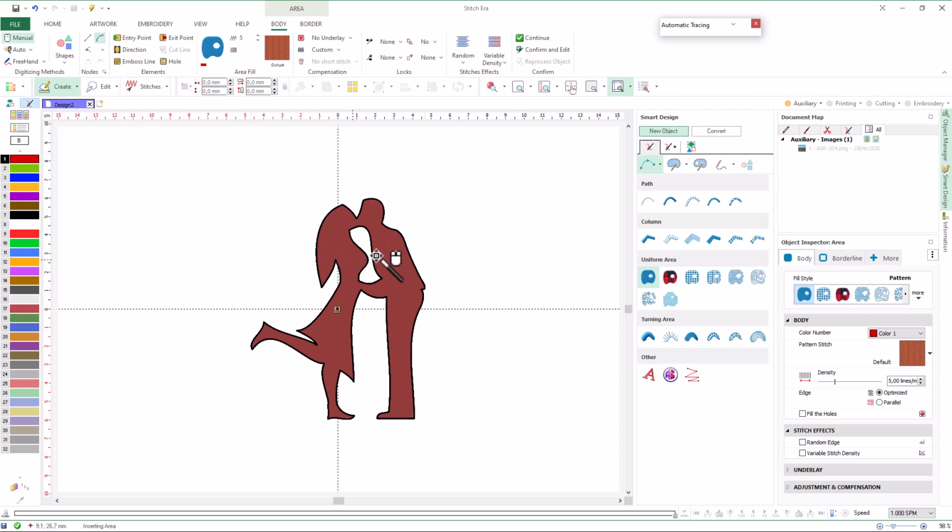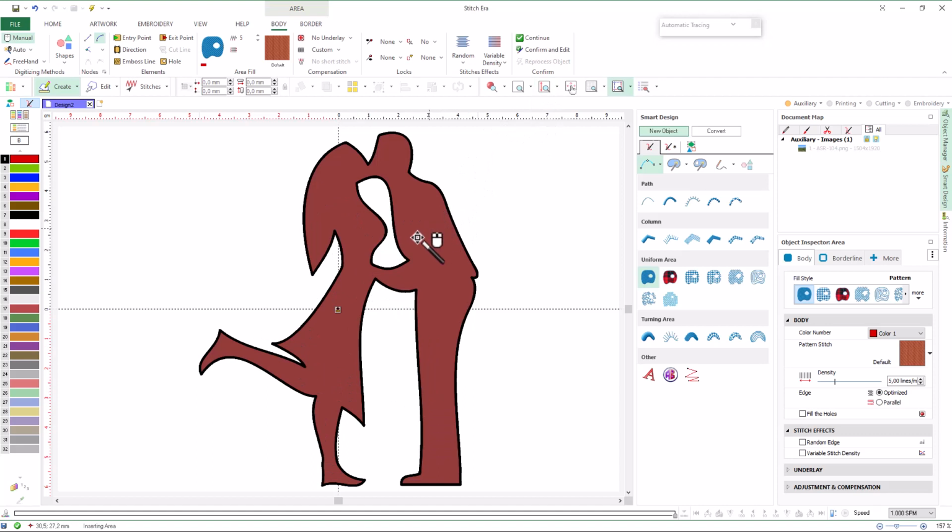When we click on a point in the image, the tool gets the color at that point and starts scanning the image following a horizontal line from left to right. This process continues until it finds an edge, that is, a significant color difference with respect to the color of the point where we clicked. It then marks that point as the start point and begins to navigate the image along that edge, keeping track of the path it is following. It stops when it returns to the marked starting point. Immediately, it presents a preview of the contour it has detected.